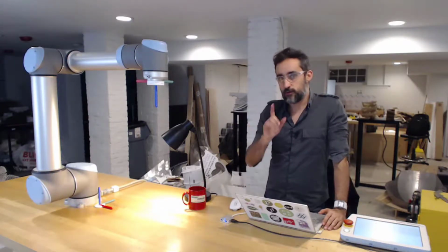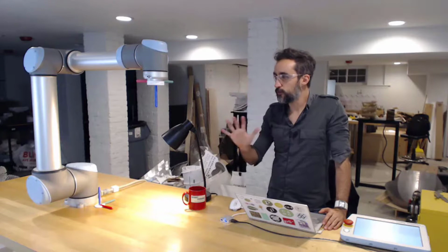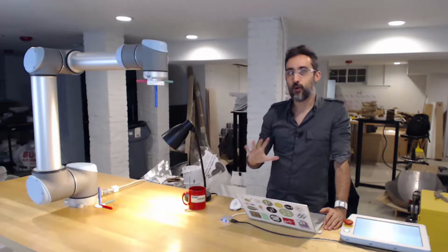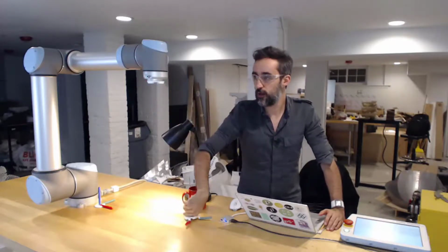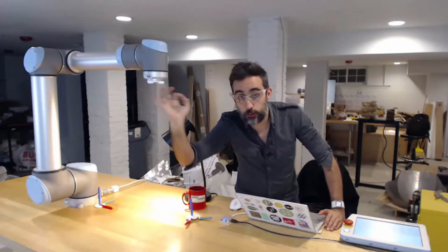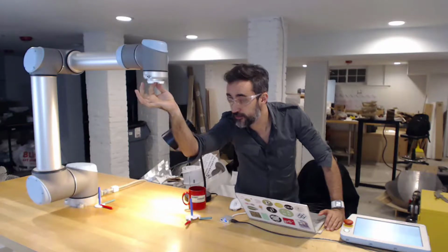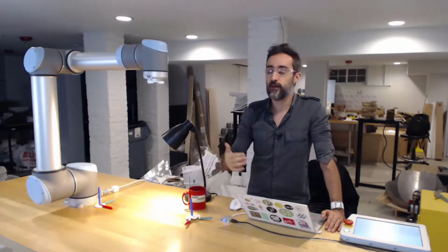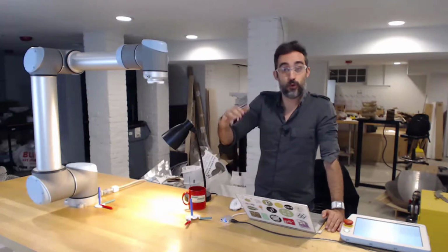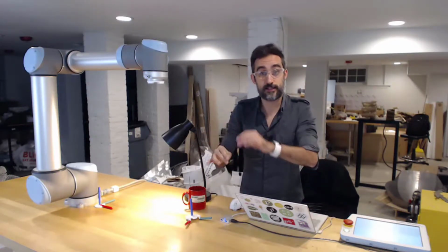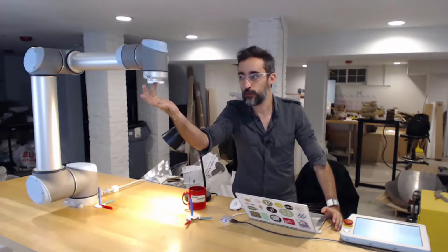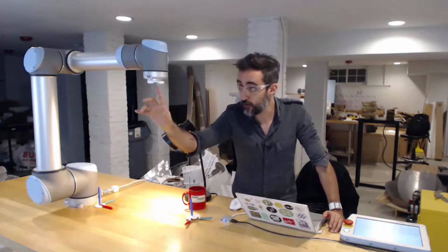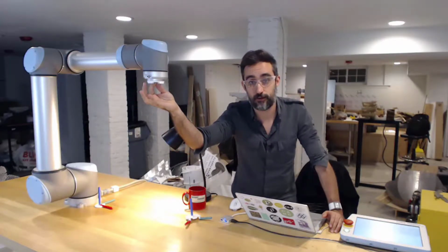Okay, so far, everything that we've done with the robot, all the motions, all the rotations, all the translations, everything was referring to this one particular point that is here at the center of the flange, and it's called the TCP, the tool center point. So when we moved, or when we set X, Y, Z, it was for this one point here, or when we rotated around a vector, it was a rotation with the center at this point here, all right?